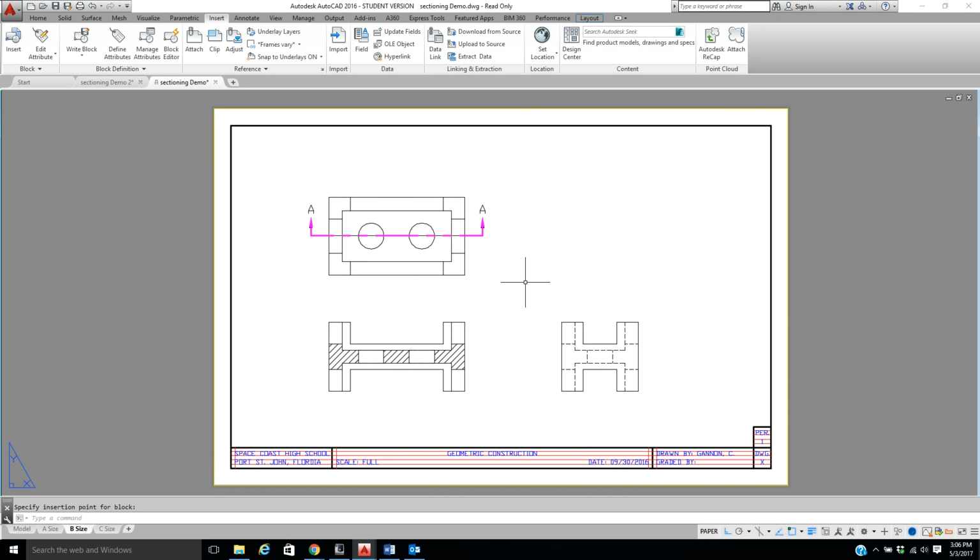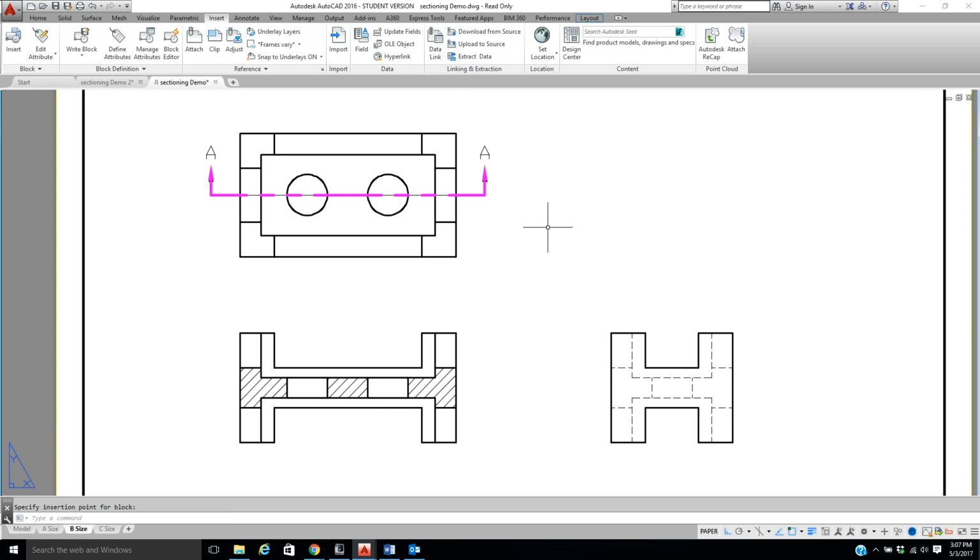So when I go to print and I restore my layer states, everything's going to come fine, and we won't actually even see these letters or these lines here. It'll be set. So the next thing you need to do is follow your sheet. Remember that little checklist. You've got everything done. Make sure you do your center lines. Make sure you do all your titles and things, and make sure you restore your layer states.